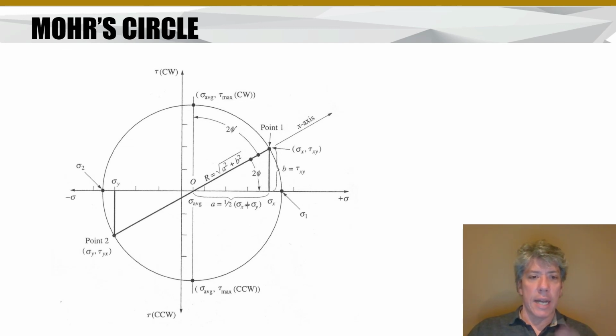I think that I scanned this and I forgot to fix it. It's a little bit confusing. When we're trying to get just the distance, notice sigma y is a negative thing, and so really I should say minus sigma y, but I've got it as plus because conceptually I just want the magnitude of sigma x and sigma y. Well, let's see. Let's make up some numbers and see what would happen. So if sigma x looks like it's to the right a little bit more, I'll count just what they've got on the tick marks.